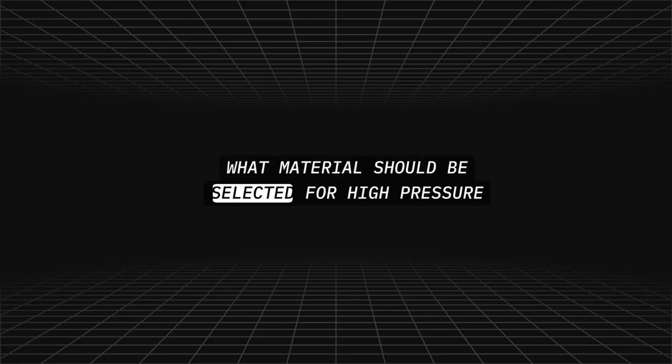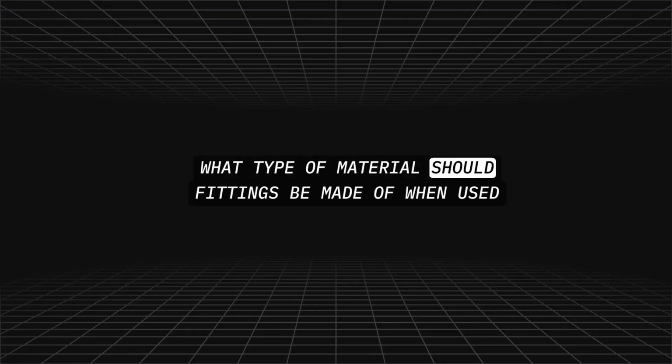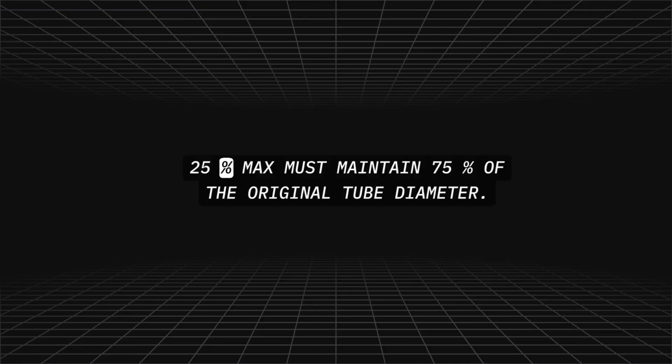What material should be selected for high pressure rigid fluid lines? Annealed or 1/4 hard, corrosion resistant steel. What type of material should fittings be made of when used with stainless steel tubing? Stainless steel. What percentage of flattening is allowed when bending metal tubing? 25% max. Must maintain 75% of the original tube diameter.